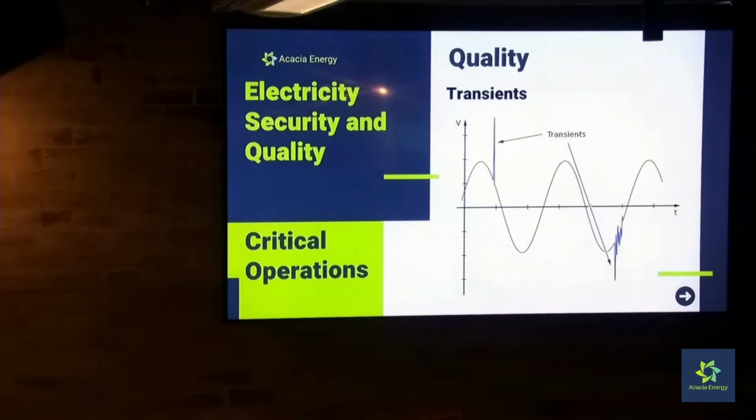And we get reflections back and forth across the line, which, similar to our harmonic distortions, constructively and destructively interfere to form a nasty little spike there as well, which again is a normal part of network operation. But if you are not protected against these spikes, they can cause damage to especially sensitive equipment. The scale on this diagram isn't fantastic.